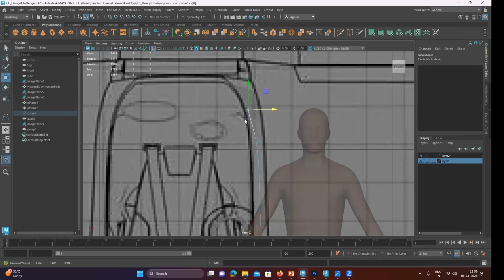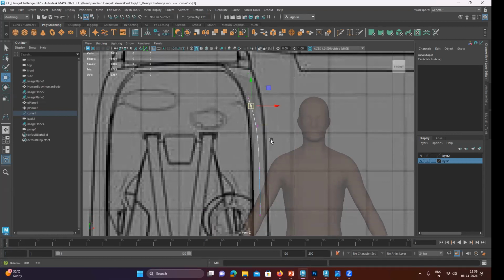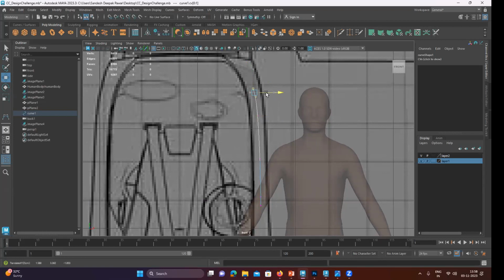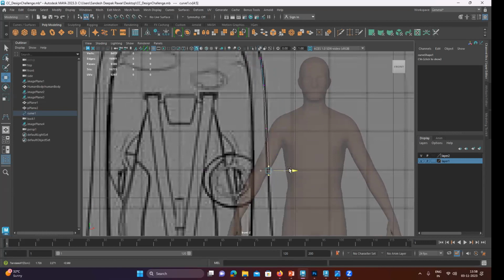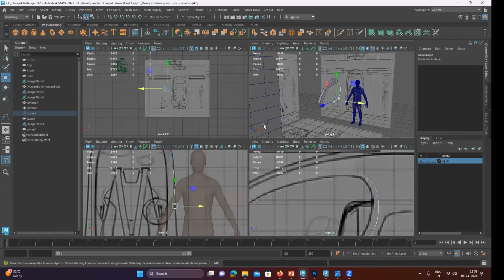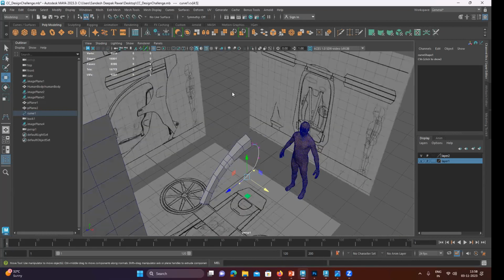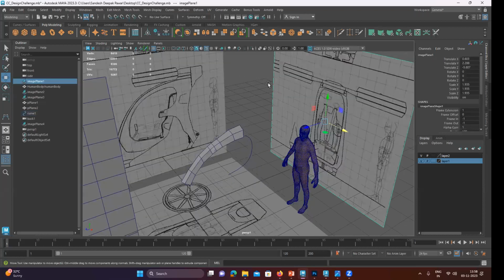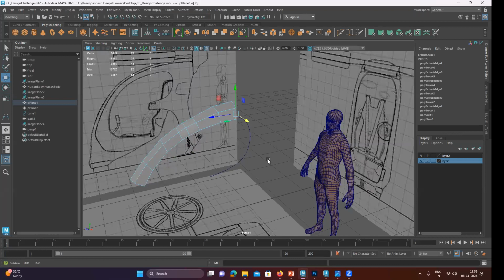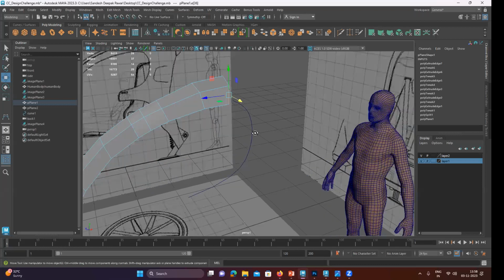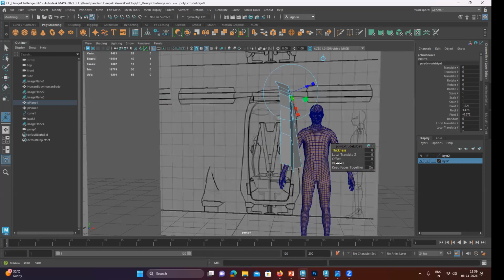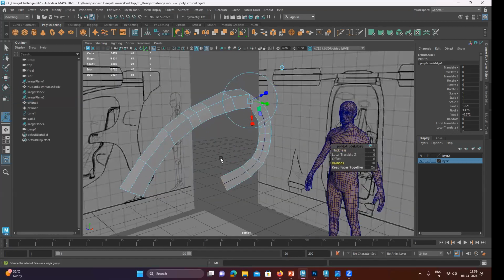Okay, so be sure to have a proper surface. Maybe you can match this outer line like this. Select this edge from where you want to extrude. Select this curve and just press extrude. That's it. So once you place extrude, the divisions are limited, and now you will get this.